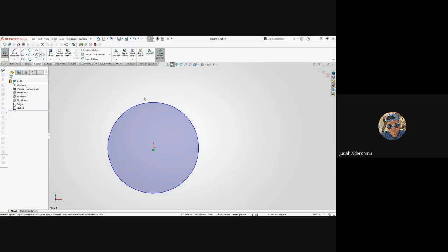Yes, I'm going to use an arc for this. I'm going to use the 3 point arc. Okay, let's start here. Then I'm just going to make this arc and this arc tangent.